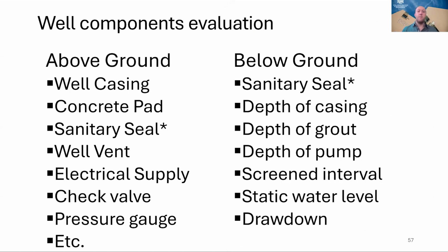And then thinking about the actual well components, you should analyze these on occasion, relatively regularly, to make sure they are all in good working order. There's, of course, well components that are above ground and below ground. And so a lot of these, you're not going to be able to evaluate very regularly. Things like your sanitary seal, depending on where it's located, maybe you can see if it's still intact. Your depth of your casing, depth of grout, depth of your pump, the screen interval, those are all things that you should be aware of. They're not going to change much.